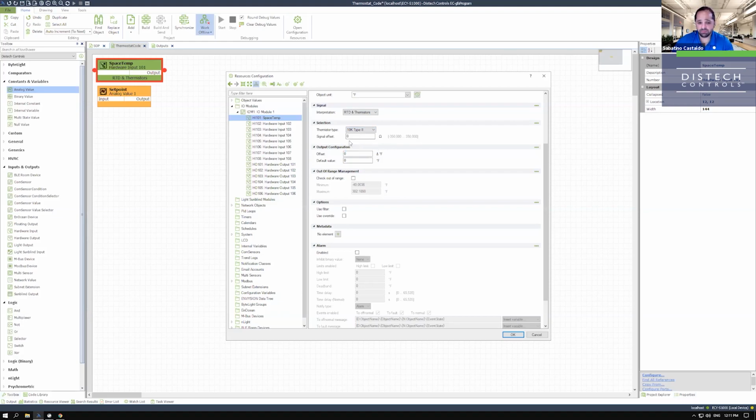For a standard type of sensor interpretation, anything else would be up to you to create, and that would be either a custom thermistor or custom type of interpretation, or just custom. Linear is basically going to be used for linearization of an input. So 0 to 10 volts, 4 to 20, 0 to 20 milliamps, etc. That'll be your linear.